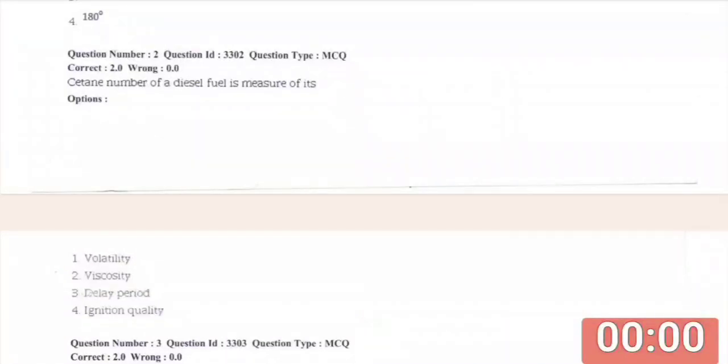Cetane number is an inverse function of the fuel's ignition delay, the time period between the start of injection and the first identifiable pressure increase during combustion of the fuel. In a particular diesel engine, higher cetane fuels will have shorter ignition delay periods than lower cetane fuels. Cetane numbers are only used for the relatively light distillate diesel oils.